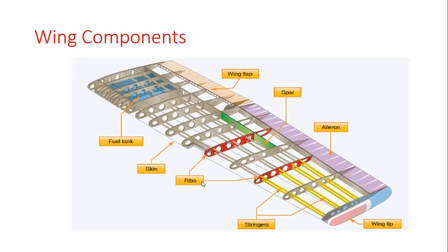Two types of control surfaces referred to as ailerons and flaps. Ailerons extend from about the midpoint of each wing outward toward the tip and move in opposite directions to create aerodynamic forces that cause the airplane to roll.